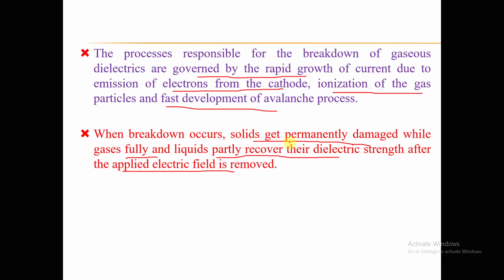It doesn't mean that the insulator, the solid dielectric material, is completely damaged. But if a tremendous voltage stress is applied to the dielectric material, and the breakdown takes place through the dielectric, then it is known as a puncture phenomenon. Okay, and the puncture itself indicates permanent damage.